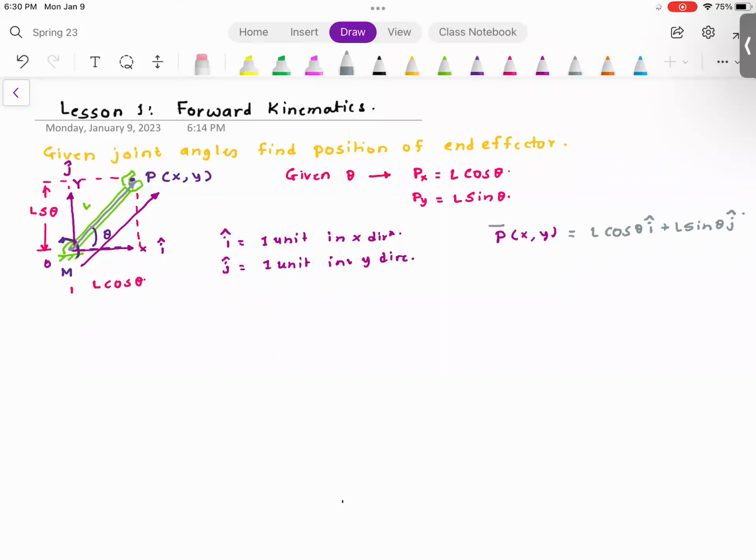Now, robots typically have two types of joints. One is a rotary joint and the other one is the prismatic joint. The rotary joint is shown something like this, and a rotary joint is nothing but a hinge. So if I were to draw the three-dimensional representation of the figure, then my robot arm is something like this.